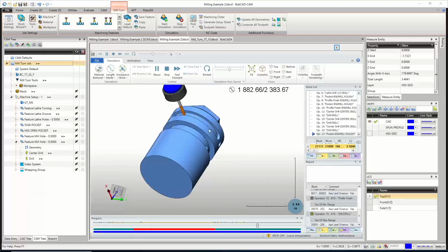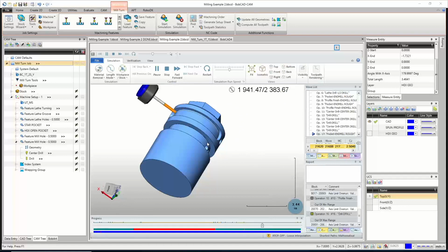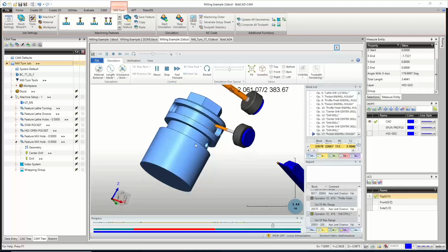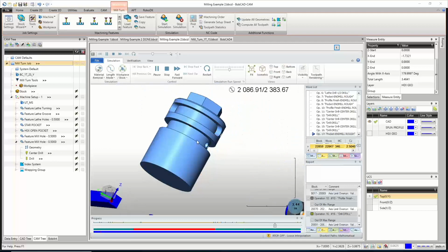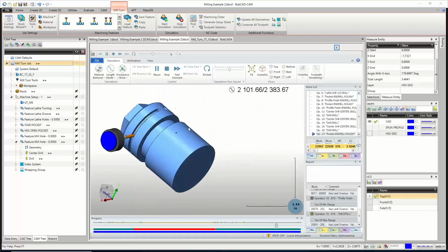And there we go, that's our first depth. I think we got 2 of those. You'll see it zigzag again down at the bottom. Yep, there's our zig, gets to depth. And then I think I went with like a 15% step over. So not too crazy on that, but now it's going to do the other side.